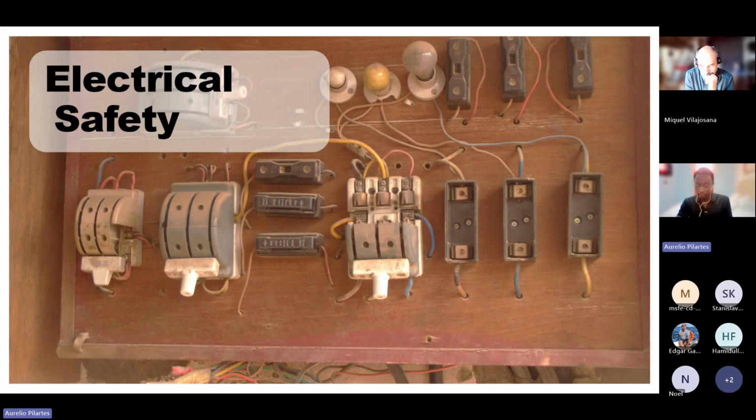And also because you'll avoid voltage limiters for all these kinds, because the voltage limiter will make a lot of stops and then start again. So it's always a good idea to use an AVR. And then for the other, more sensitive devices, as I explained, a UPS should do.